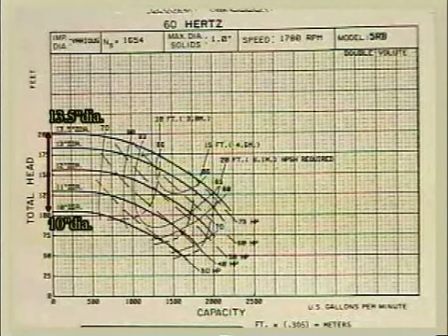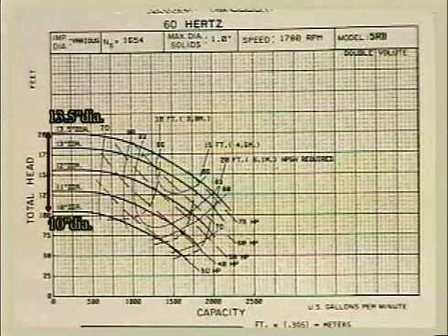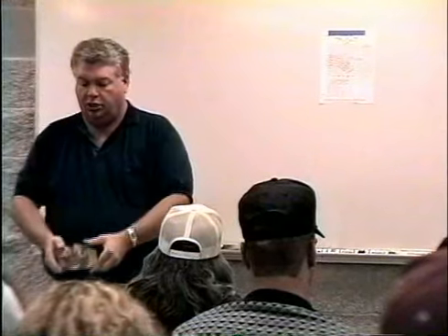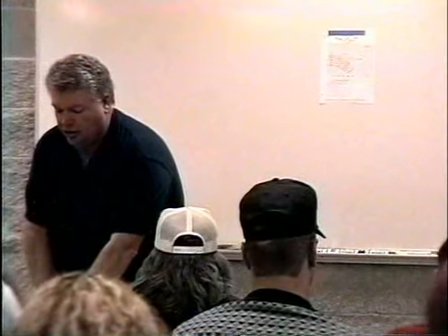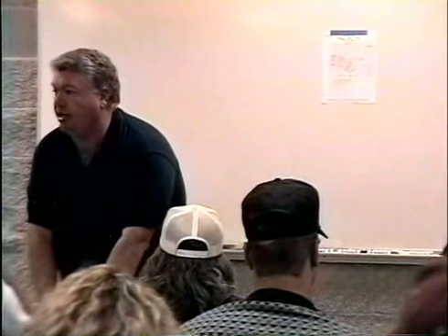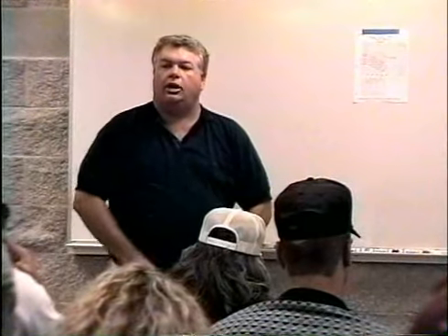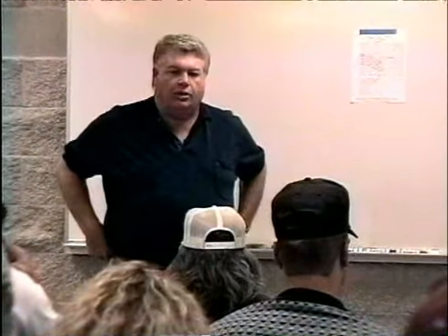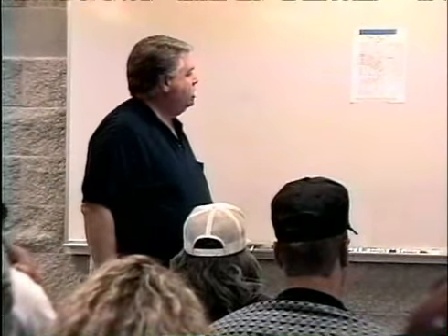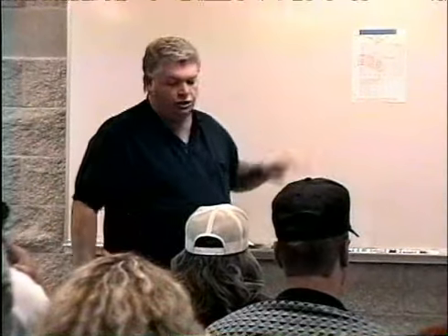It comes as a 13.5-inch diameter impeller for that particular pump, and then they simply put it on a lathe and turn it down if they want it smaller to fit the condition that we're after. So we can pick a condition and make some decisions about it.